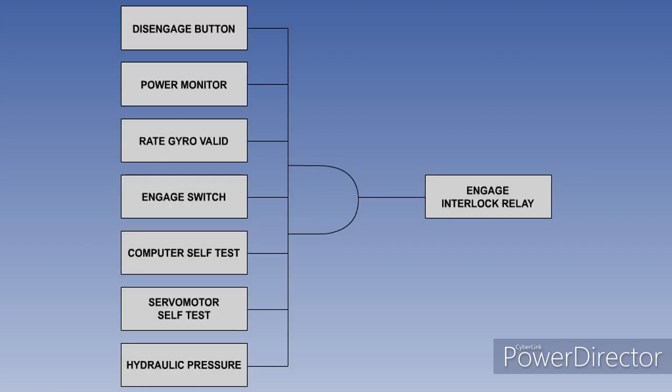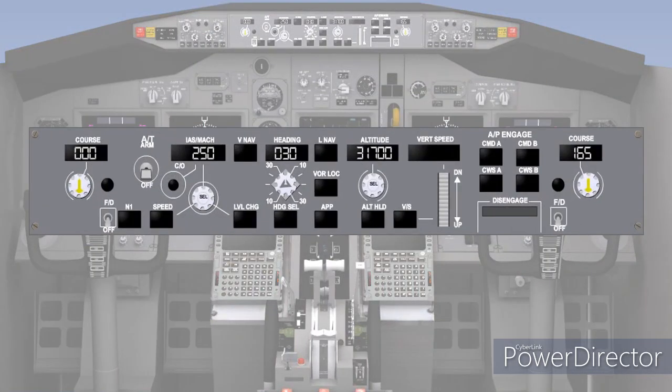In this lesson, we will look at the different types of actuators used in autopilots, why automatic synchronization is provided, the necessary interlocks that have to be made before the autopilot will engage, and the reasons an autopilot will disengage. We will then look at the autopilot function auto trim and a non-autopilot trim function, Mach trim. Next, we will examine the autopilot interface. And finally, control wheel steering.